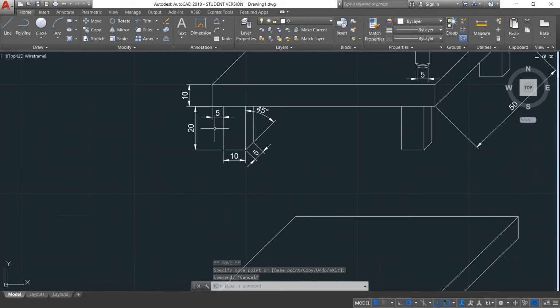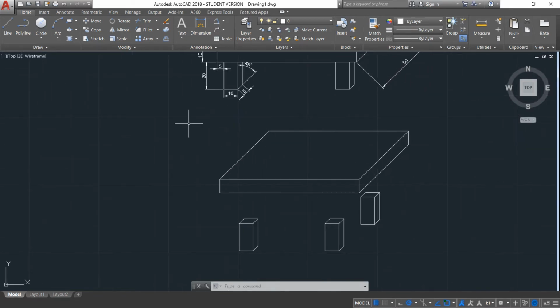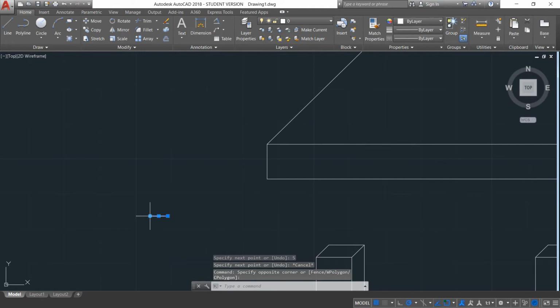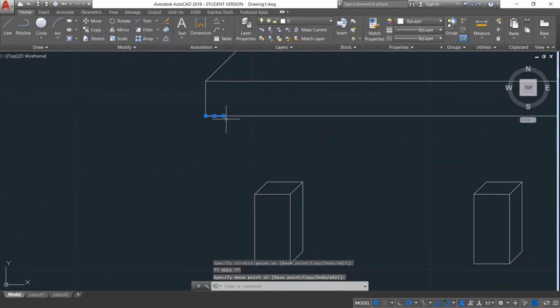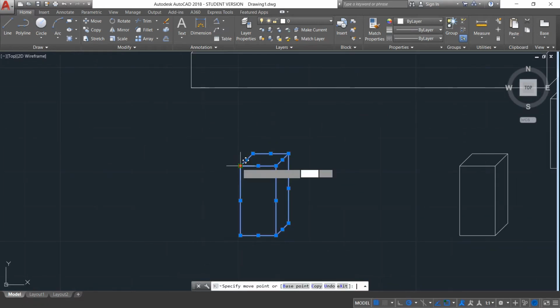As you can see, there's a bit of a gap between the legs and the edge of the table, which is 5 millimeters. So what we want to do is add 1 more line. Just measure it anywhere within the 5 millimeter length. Select the line and go to the edge of the table. Now we have a set point here for us to place our first leg.